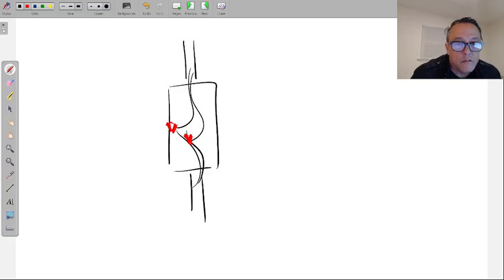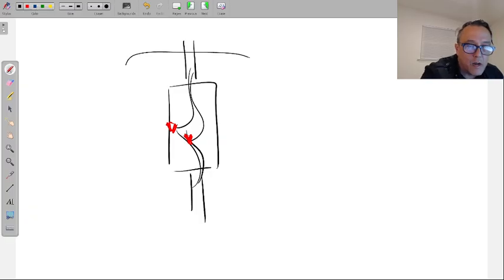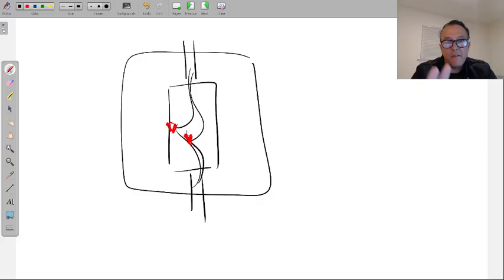So now you have a choice. What do you do with these wires? Well, the correct thing to do is they still need to be accessible, even though you moved the switch down the line or somewhere else on the wall. Because they're spliced wires, I still need to be able to get to them. In other words, you're not just allowed to put drywall over this and bury the wires in the junction box, thinking we don't really need them for anything ever again, and just put some drywall over it like they were never there.